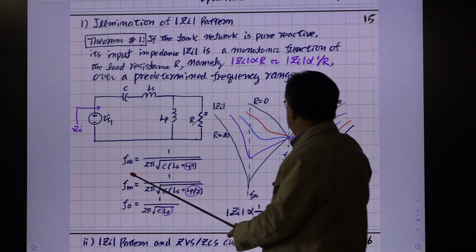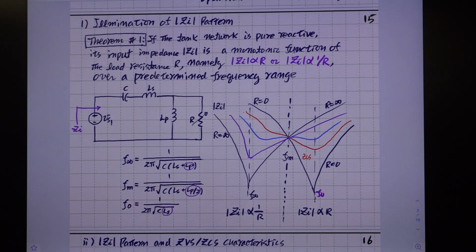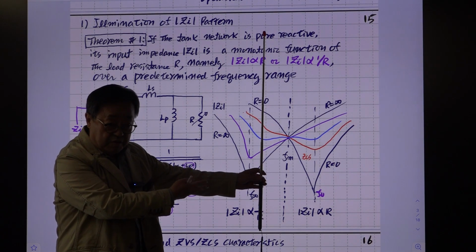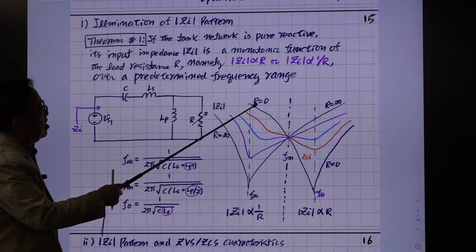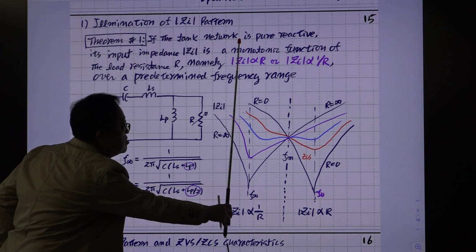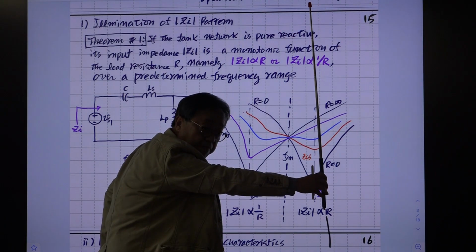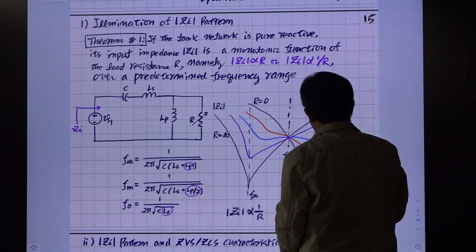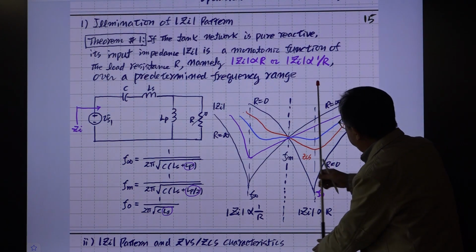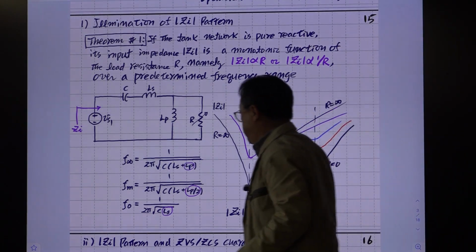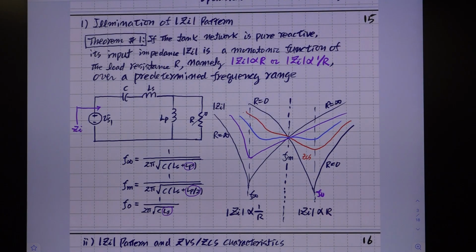All right? So because of this, we prove this. We prove this using EET, the external element theorem. Maybe some of you heard the term external element theorem. We prove that, so this is the pattern we predict, and it is true. Everything is bounded between. It starts with R at 0 and R is increasing. At a particular frequency, if the magnitude of GI is decreasing, it keeps on decreasing up to this point. In the other region, if you increase R, then GI is increasing, and it keeps on increasing at this particular switching frequency. That is the meaning of this. Okay? So this is very important. It provides very valuable information about the efficiency of this resonant converter. Their story is coming later.